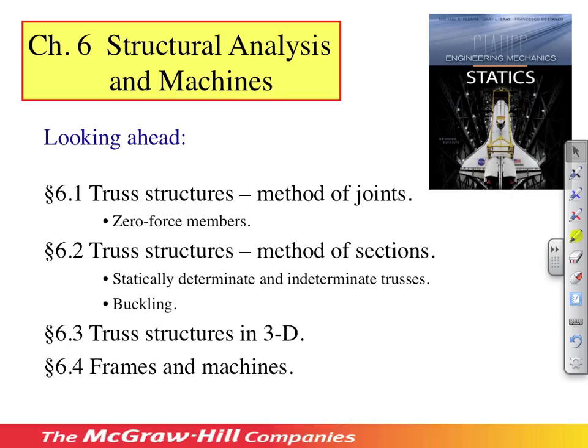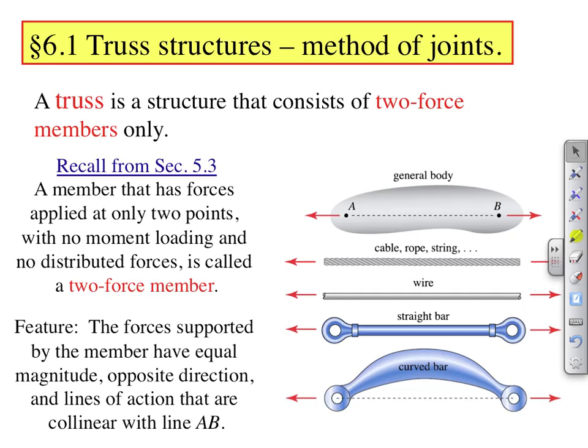Even though machines are intended to move, our interest is confined to temporary configurations where we can use the equations of static equilibrium to determine loads transmitted by the machines. A member that has pinned ends and no ability to react moments, and that just transmits a force between those ends is a two-force member, and it is already in equilibrium. If the weight of the member is significant, then there is an intermediate force between the pinned ends, and it can't be treated as such. To treat it as a two-force member, we either have to apportion its weight to its ends using equivalent force system principles, or ignore its weight.